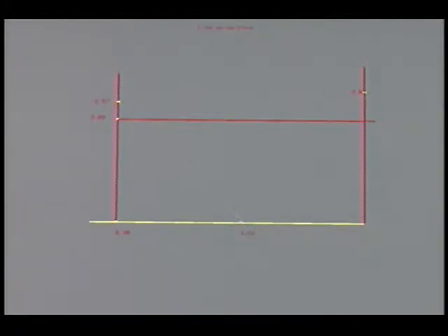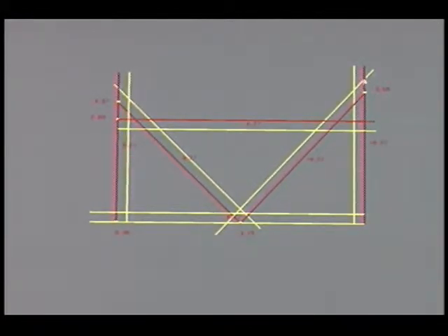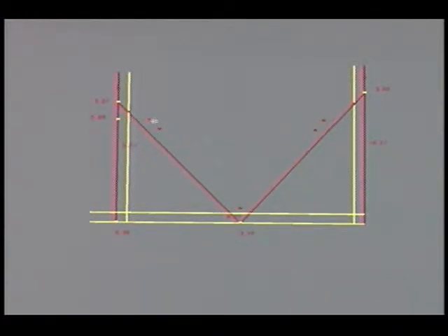In addition, the system infers a variety of geometric constraints between primitives as they are drawn. Here the user insets one line and then repeats that operation for a number of additional lines. All of these lines are constrained to be inset by the same amount. The user continues the construction by identifying key intersection points in the 2D drawing. Then the user deletes the lines that define the intersection points in order to draw more precise line segments.